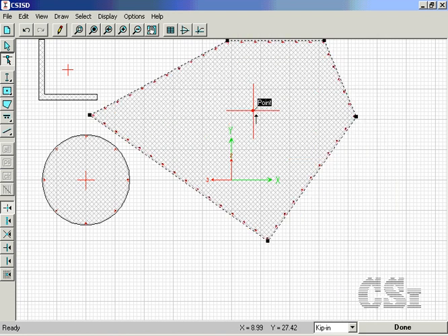At this point, it should be noted that all three of the drawn shapes constitute a single section, and though one of the shapes is steel, the Section Designer utility will calculate properties for eTabs based on the equivalent base material of concrete. It should also be noted that only the member 2-3 axes have meaning for eTabs, as the XY axes shown are local references only.